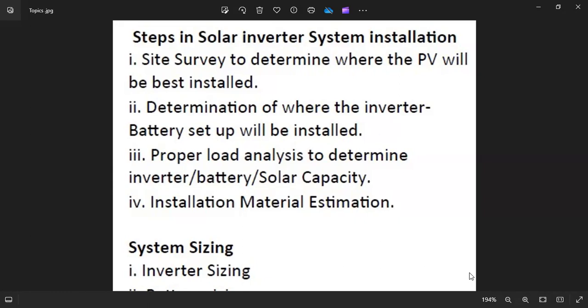You understand the point? So that is why, number one, if you're using the tubular battery, you need to install it in a ventilated place, please. It emits hydrogen, though in little quantity, but when it's in a confined space, it will occupy that space, and a little ignition can cause fire incidents. So that is that for the tubular battery. What we can get from there is that a tubular battery needs to be installed in a ventilated area.